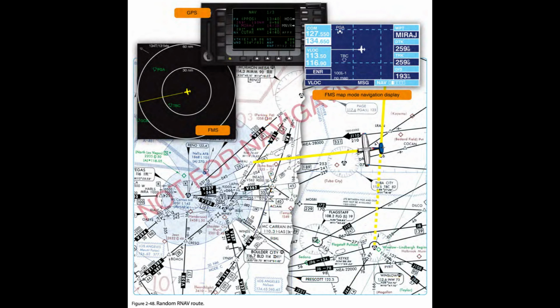Monitoring of navigation facilities. VOR, VORTAC, and Instrument Landing System, ILS, facilities, as well as most NDBs and marker beacons installed by the FAA, are provided with an internal monitoring feature. Internal monitoring is provided at the facility through the use of equipment that causes a facility shutdown if performance deteriorates